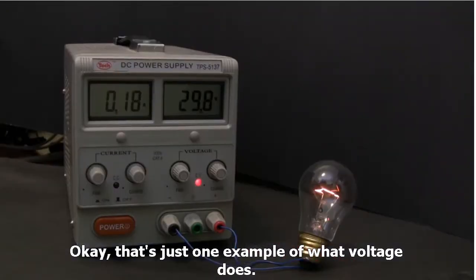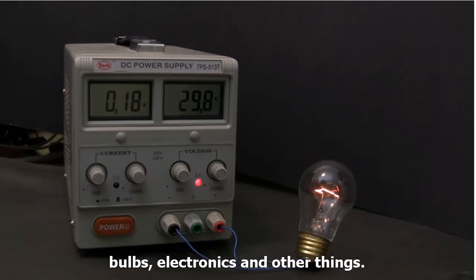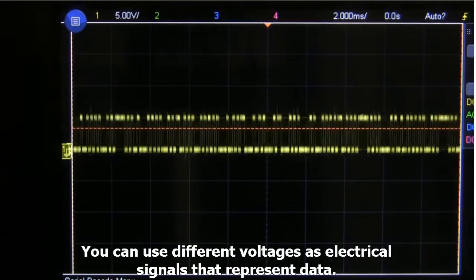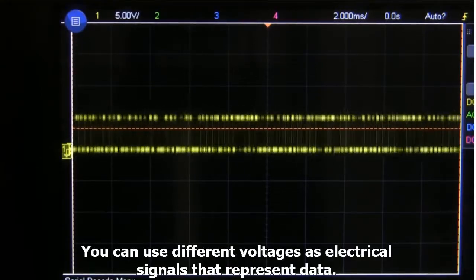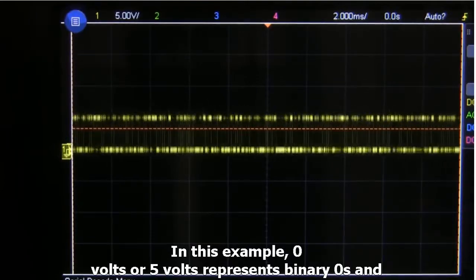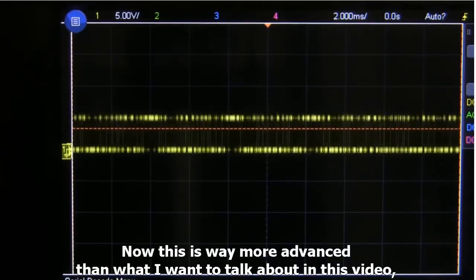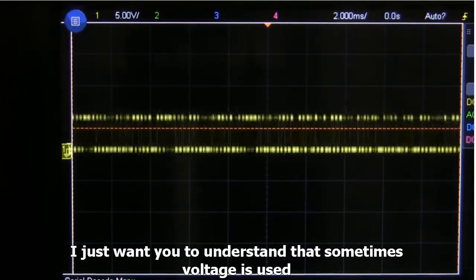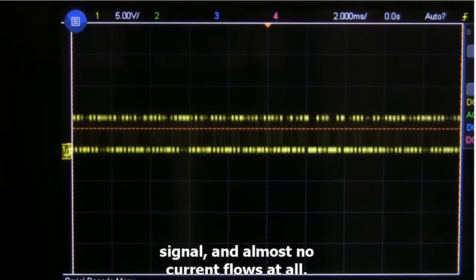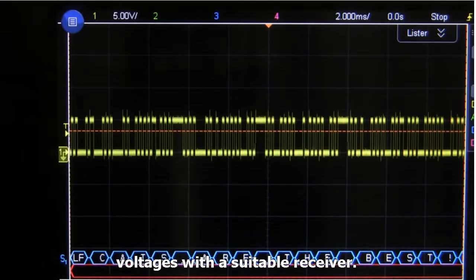Okay, that's just one example of what voltage does. You can use a voltage source to power motors, light bulbs, electronics, and other things. Another important example of what voltage can do is carry useful information. You can use different voltages as electrical signals that represent data. In this example, 0 volts or 5 volts represents binary zeros and ones in a communication system. Now, this is way more advanced than what I want to talk about in this video. I just want you to understand that sometimes voltage is used to power things that draw high amounts of current, but you can also use voltage as a signal, and almost no current flows at all. You just create the changing voltages with a transmitter and detect the changing voltages with a suitable receiver.